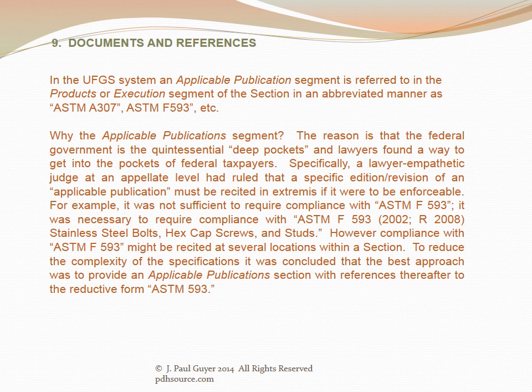For example, it was not sufficient to require compliance with ASTM F593. It was necessary to require compliance with ASTM F593 2002 revision 2008 stainless steel bolts, hex cap screws and studs.